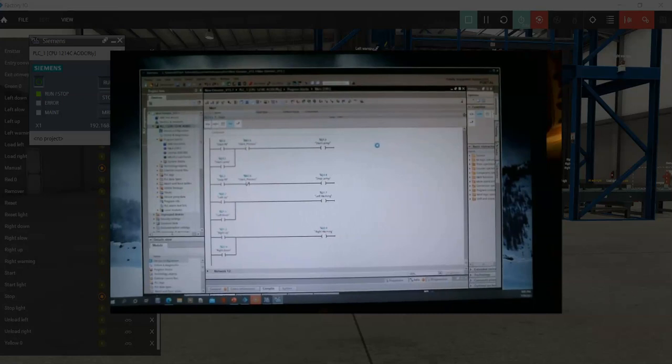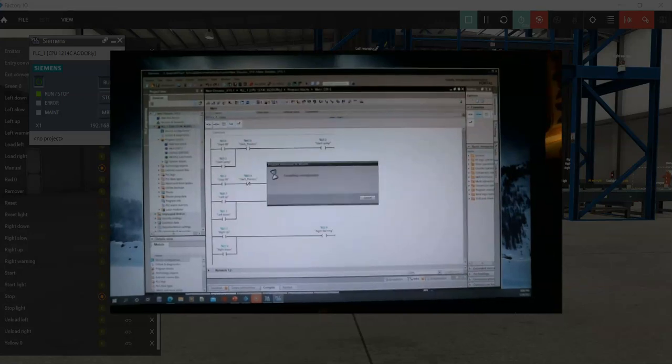And you can see, in the way it's set up, you can't see the full IP address, but it says it's in the stop mode. This goes between amber and green. When it's amber like this, it is in the stop mode. But this does have our IP address for the PLC. And right here it's saying it's compiling the configuration.